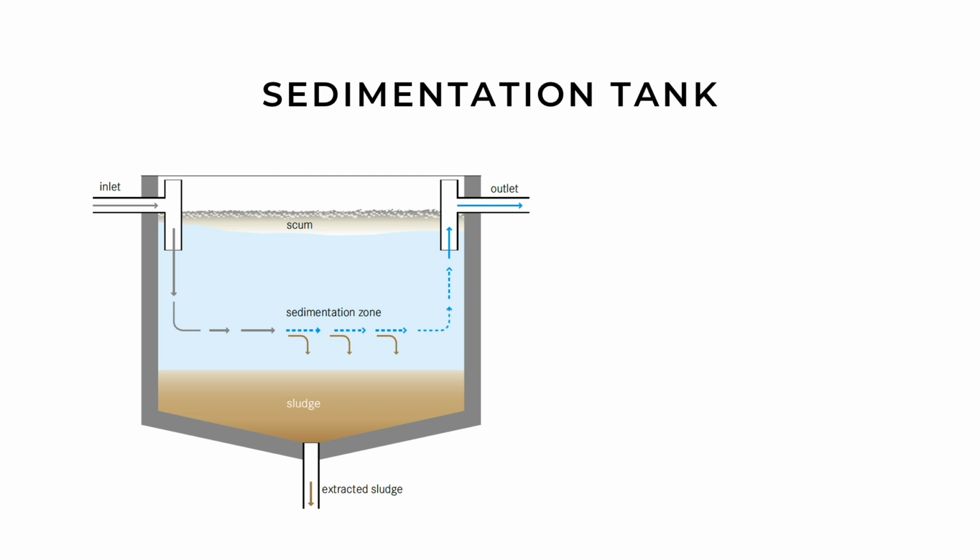Sedimentation tanks are also called settlers, clarifiers, or settling basins. Their main purpose is to facilitate sedimentation by reducing velocity and turbulence of the wastewater stream. The solids that deposit at the bottom, called sludge, need to be removed periodically to ensure that the unit works under designed conditions.